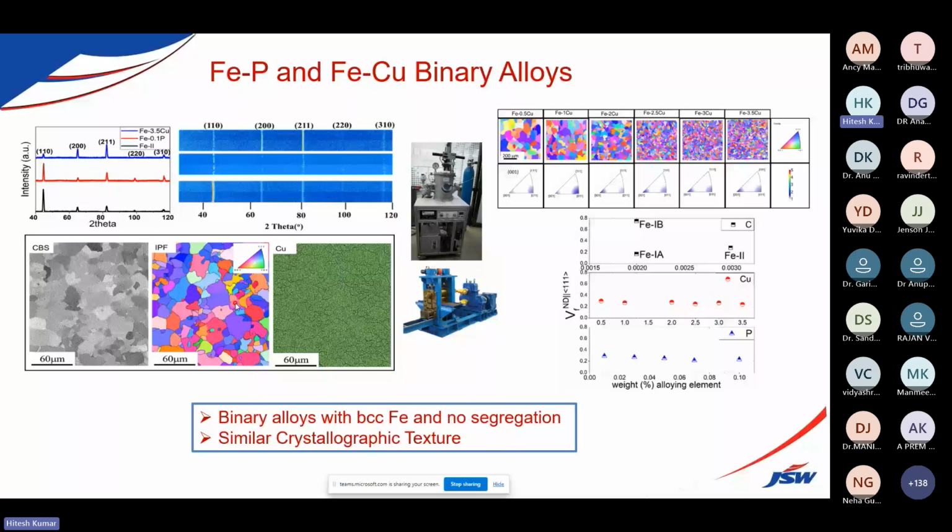We got some good nanophase precipitates at the grain boundaries, which I will show you later. The SEM showed a uniform distribution of copper throughout the matrix, with no inhomogeneity, so the alloy is homogenized throughout the material.